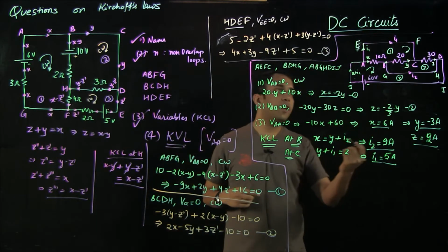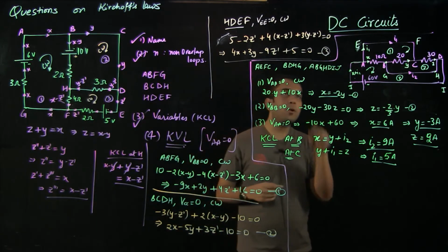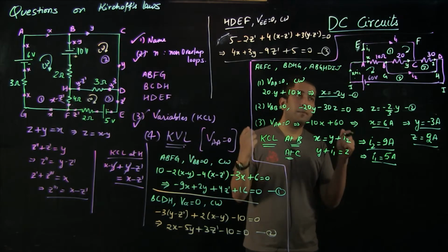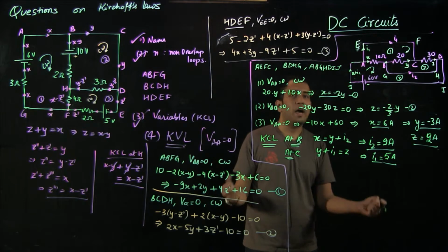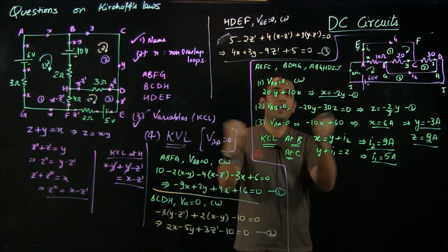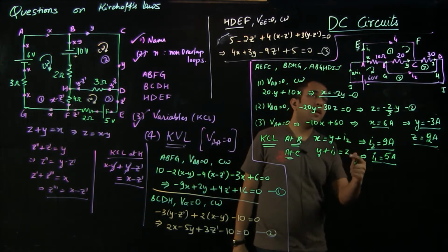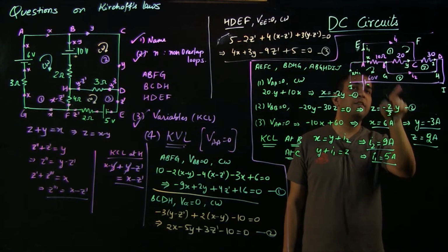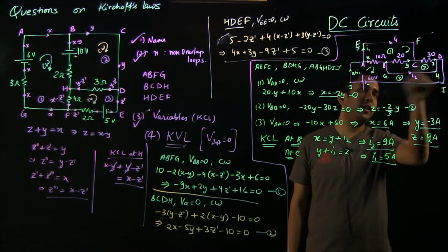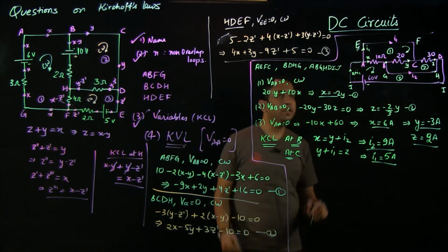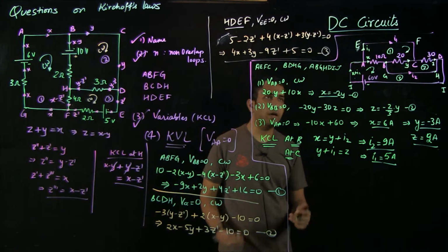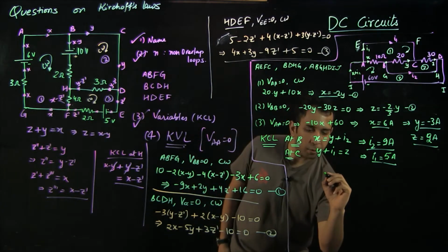So what we can effectively do is use one of the properties of the zero resistance wire, that is its flexibility, that because there is no potential difference, I can either shrink it down or I can expand it. And similarly, we can also identify a second zero resistance wire which is there between B, G, H and D. So we'll try to shrink them down and see what the circuit looks like after that.